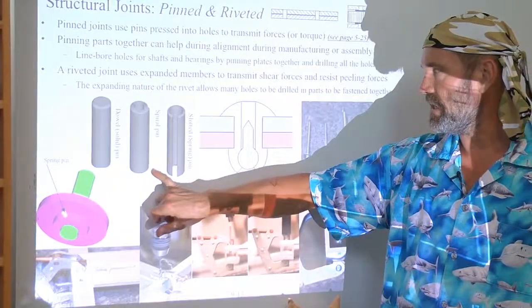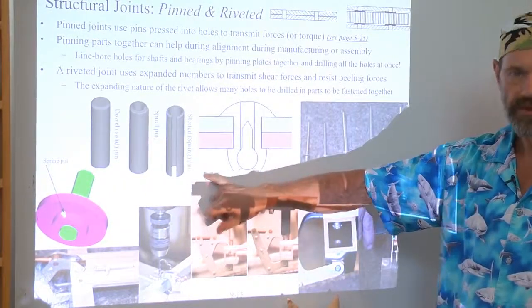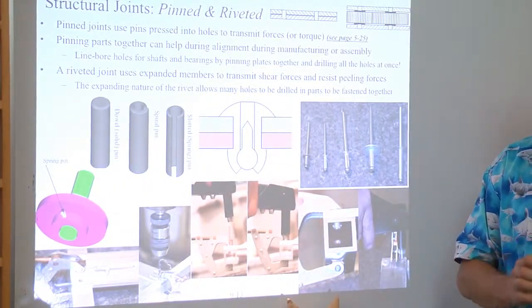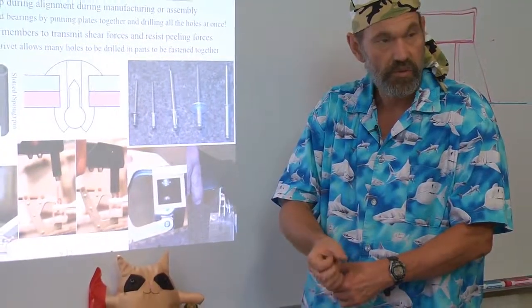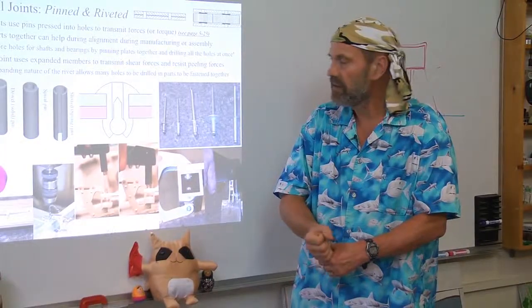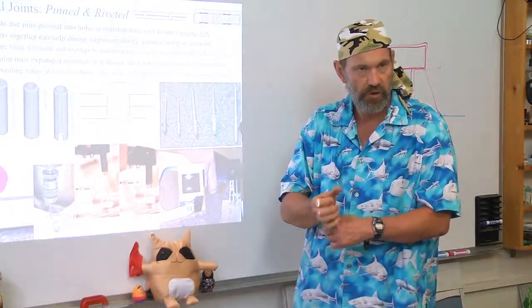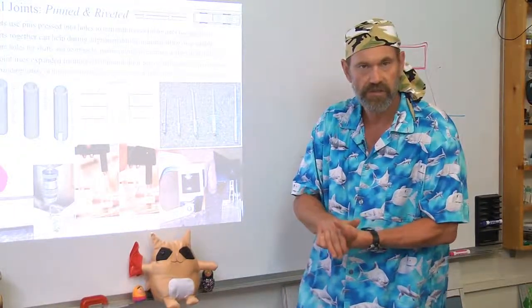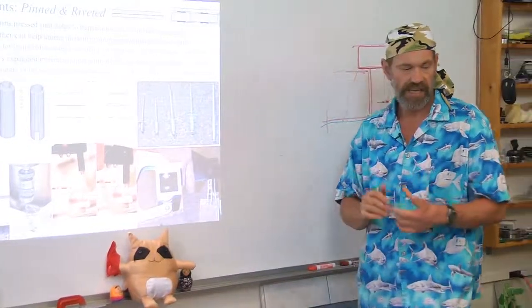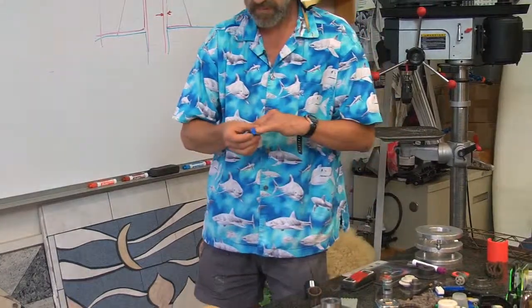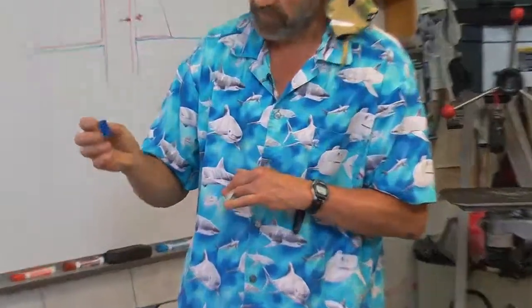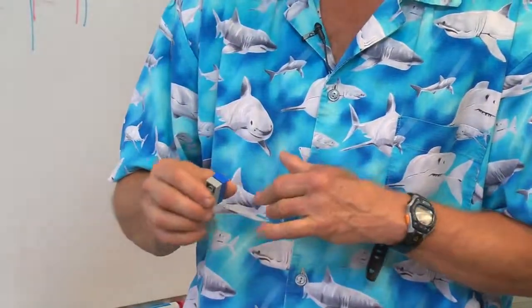A spiral pin or a slotted spring pin is pressed into a hole, but the spring has radial squishiness, radial spring, such that it can accommodate to fill the hole and often slightly misaligned parts. So it acts like a Lego in terms of elastic averaging between the receiving end and the pins.